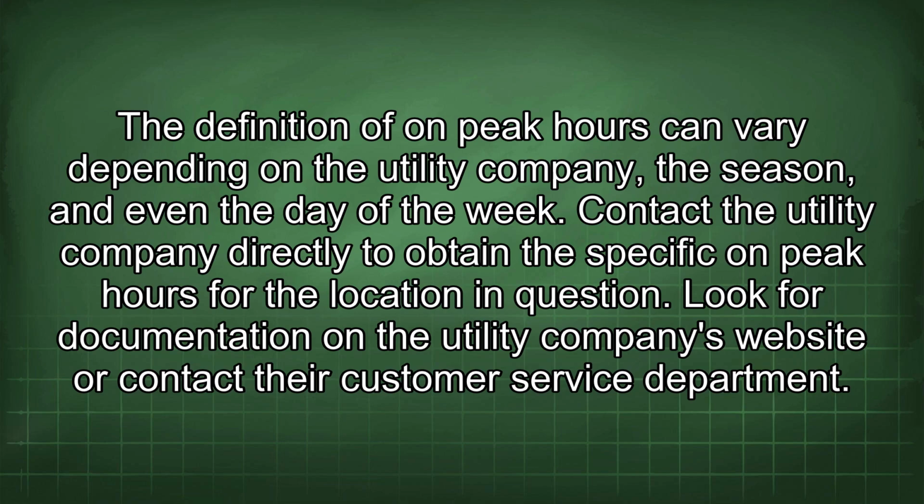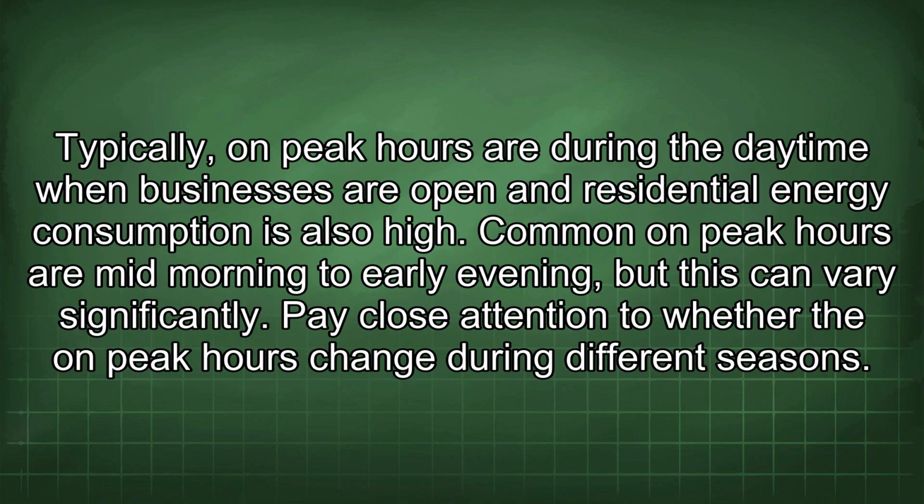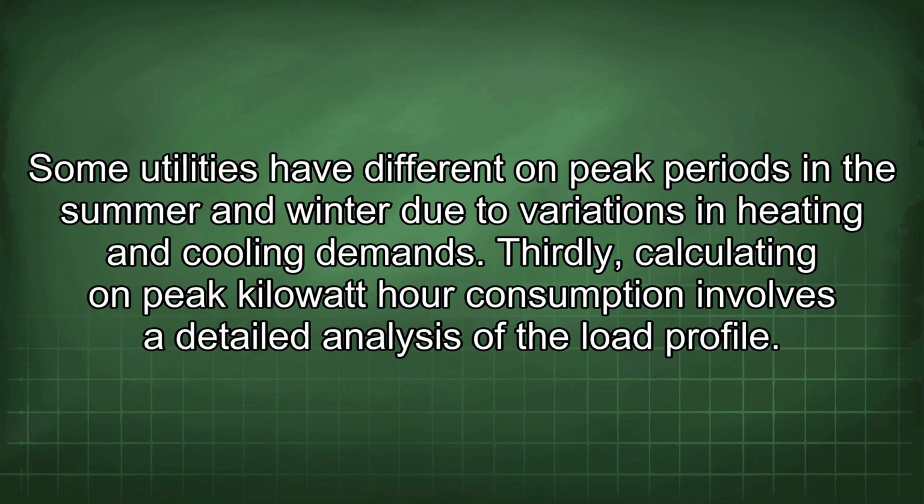Look for documentation on the utility company's website or contact their customer service department. Typically, on-peak hours are during the daytime when businesses are open and residential energy consumption is also high. Common on-peak hours are mid-morning to early evening, but this can vary significantly. Pay close attention to whether the on-peak hours change during different seasons. Some utilities have different on-peak periods in the summer and winter due to variations in heating and cooling demands.